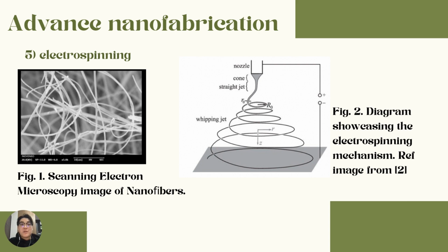This is the electrospinning step. Before electrospinning nanofibers, a polymer solution with the necessary components is created. This solution is placed into a syringe and slowly injected. The solution-holding needle is connected to the grounded collector with high voltage. The needle tip shoots liquid due to electrical force.